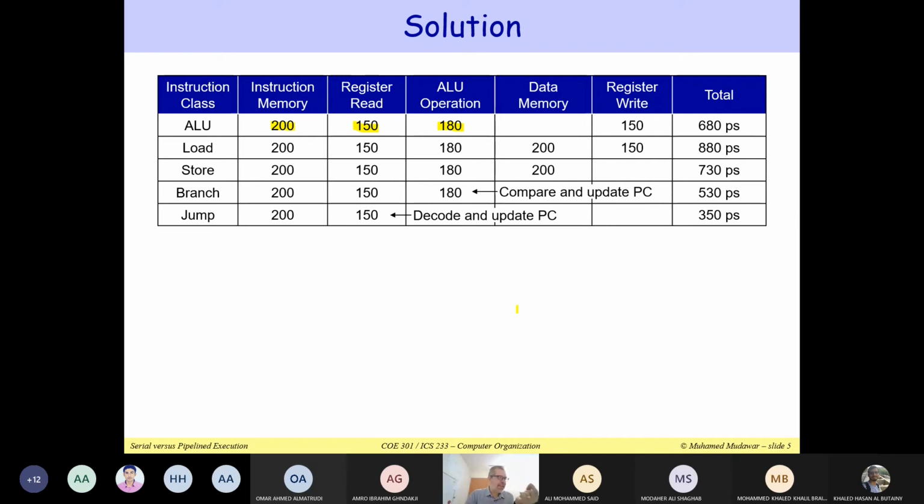So we go by the longest delay, meaning the most significant bit. This is basically circuit analysis, how you analyze the delays inside the circuit. Is this clear? When I put just a single number here, it does not mean that all the bits are produced at the same time. No, some bits will be produced even before 180 picoseconds, but we go by the longest delay.